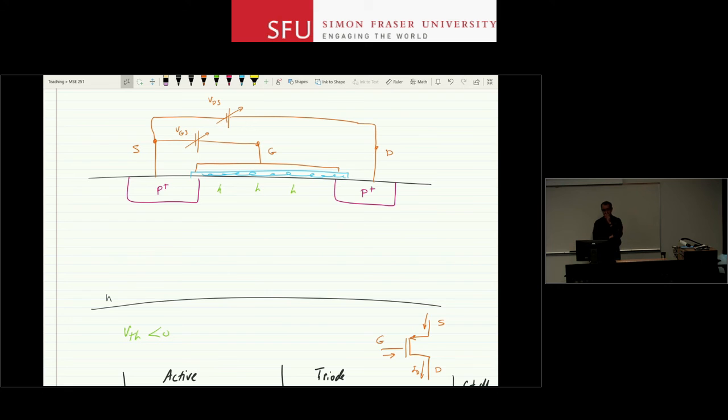And what they do is that, well, if you take an N-type wafer, you can only make P MOSFETs on it. Or if you take a P-type wafer, you can only make N MOSFETs on it, right, because of the dopings that you need. But in these technologies, what they do is that they create these little wells. Let's say you have a P-type substrate and you create an N well on that P-type substrate, and you make your P-type transistors inside that well, and N-type transistors everywhere else on the substrate. And you create these devices side by side, make connections to each other. Now, in the same technology, you have access to N-type devices as well as P-type devices.